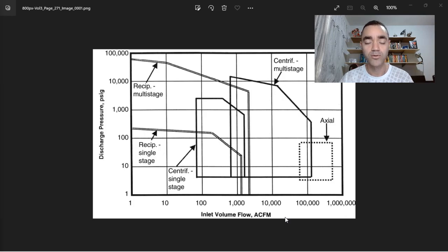So most often you will see a compressor for 2000 normal cubic meters per hour or 2000 standard cubic meters per hour. And that means you have set the conditions of temperature and pressure. And the conditions of temperature and pressure are not necessarily the same as your process conditions.